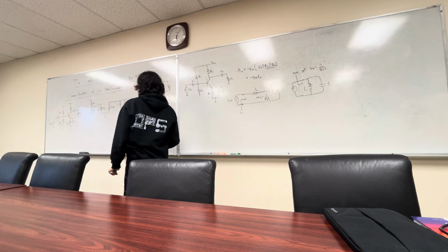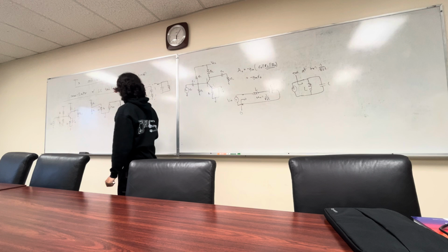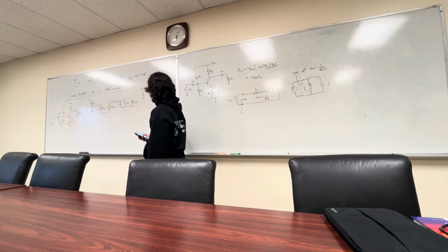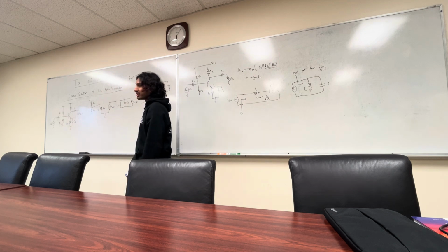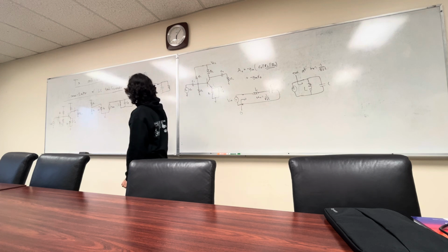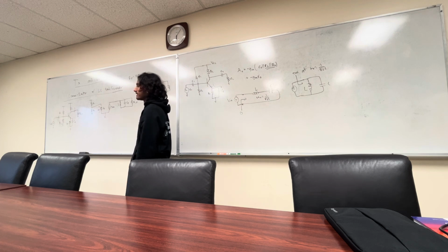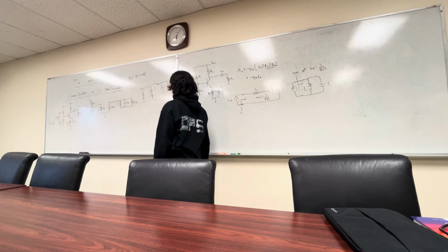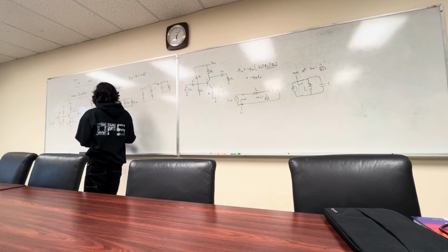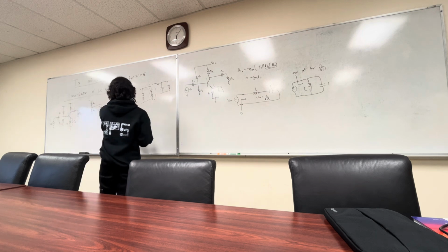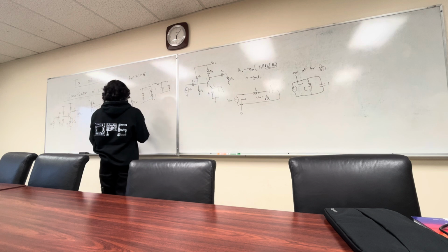Let's assume we have a pretty high quality factor, we use good enough components that have a higher quality factor. And from here we can surmise that RP is going to be decently larger than RS, right? So if Q is, let's say, what's a good Q value, we used 20 to 30 before, right? So for our oscillators, Q is 20 to 30, even like 10, the RP is like 100 times larger than RS. So we can reasonably assume this is going to be much larger than RS. That's our first assumption.